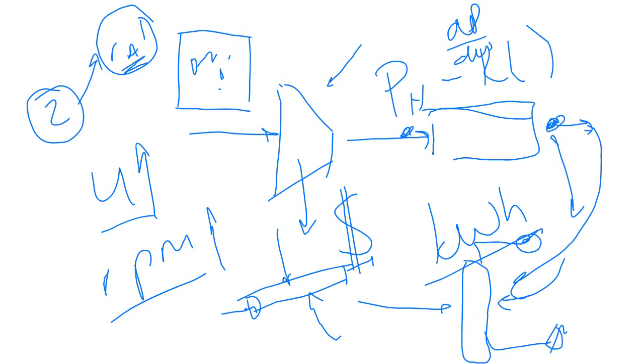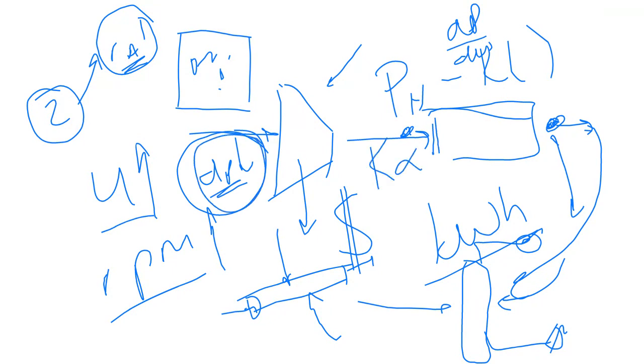Higher velocity to increase kc. Yes, and we definitely, look, we can also decrease dp, absolutely. So if I decrease dp, I definitely increase my kc. Great, somebody's watching my videos. So if you decrease dp, once again in the Ergun equation, if you remember the Ergun equation, that value is inversely proportional to the particle diameter. So pressure drop is never our friend.